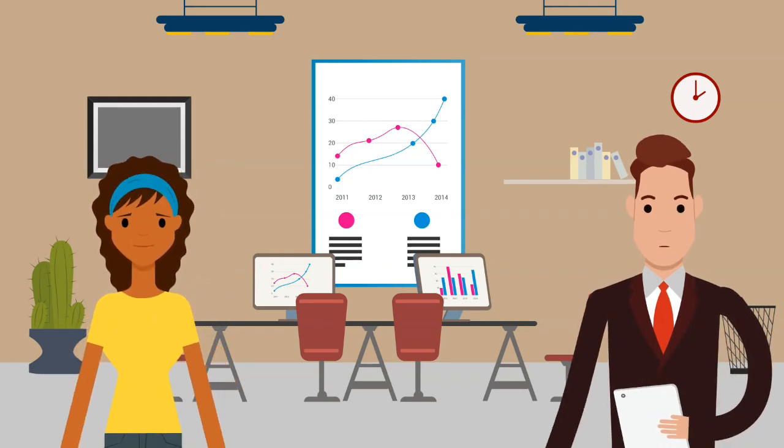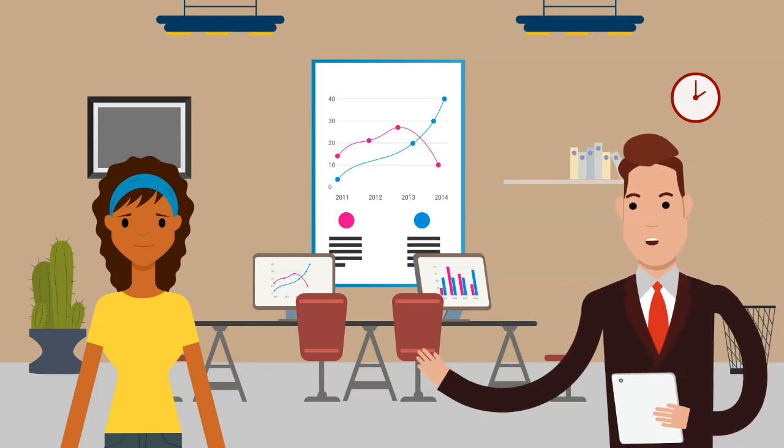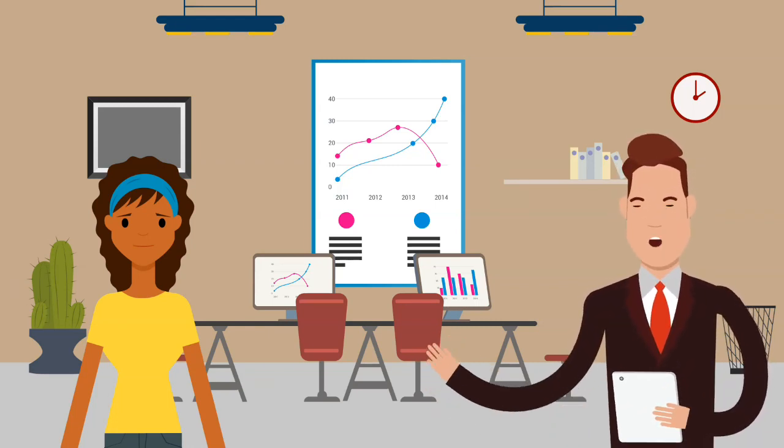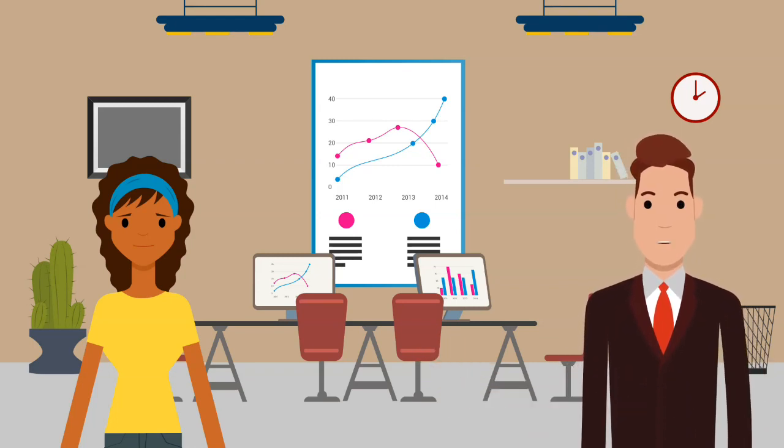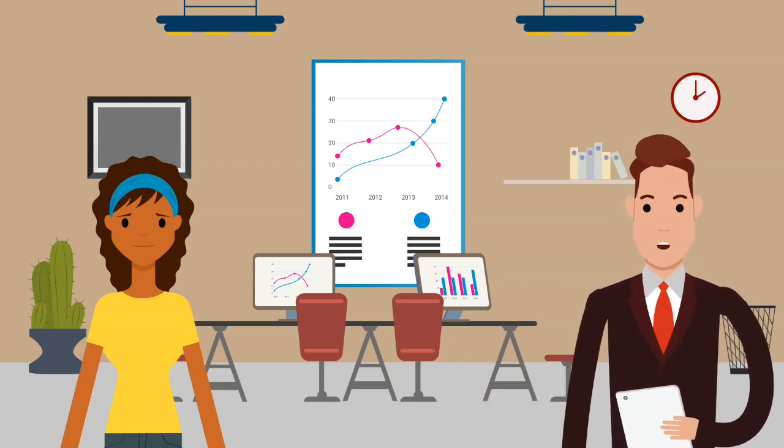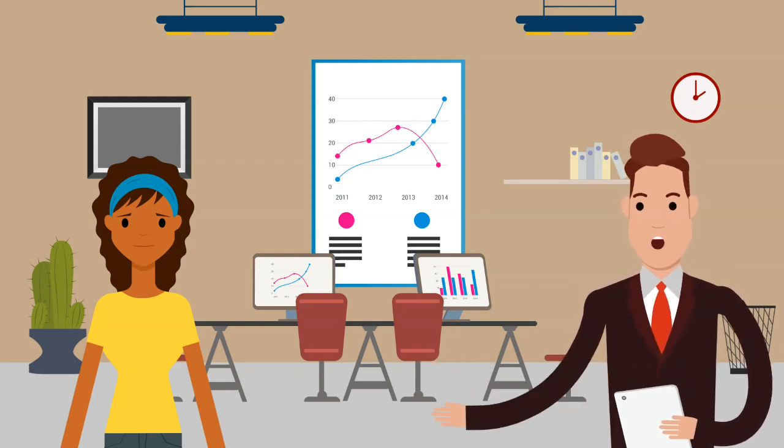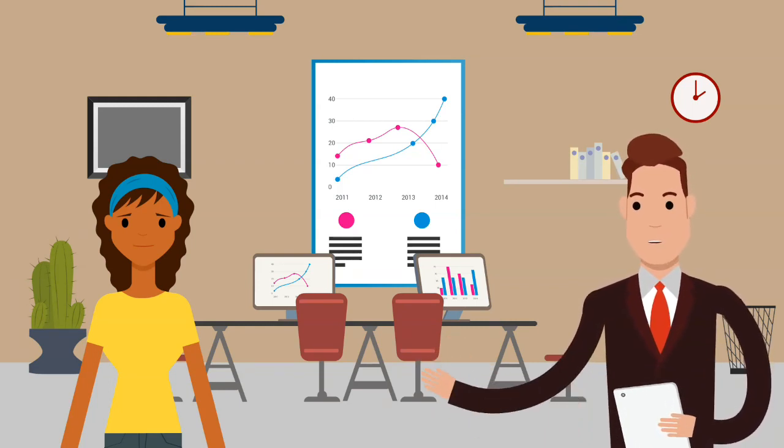The subjective method is based on a method which has been taught in industrial engineering textbooks for many decades called systematic layout planning, or SLP. This method uses the opinions of people using the workspace, and the opinions of other key stakeholders. Each person providing an opinion ranks the importance of the location-to-location relationships on a scale of 6 levels of importance.